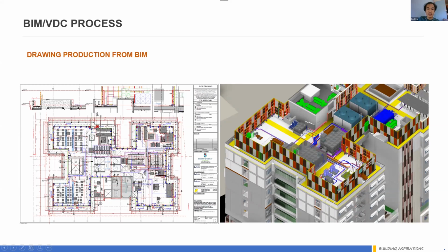In the consultant drawing, you will never have this kind of detail, because the consultant drawing will show a cutting wall screen, but they will not have the backing structure and all these requirements. Because this one goes through our internal PE drawing, I will force our subcon to give me more, based on your PE drawing.